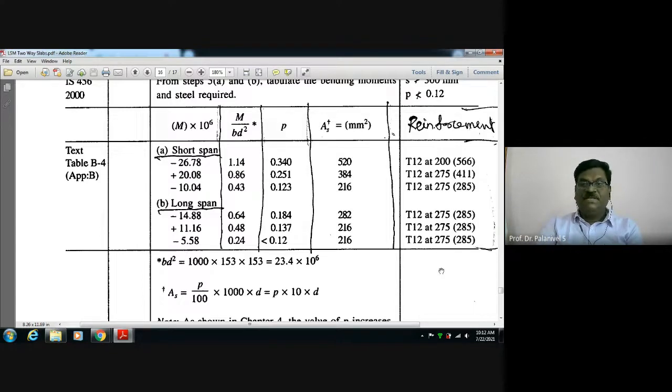But see here, practically applying them on the field, there are difficulties involved. It is easy to compute. Just think over, in a slab along the short span direction, at mid span, the spacing between the reinforcement should be 200 mm. When it comes to the continuous edge and discontinuous edge, the author has said 270 mm spacing.